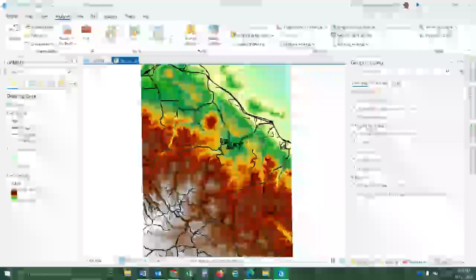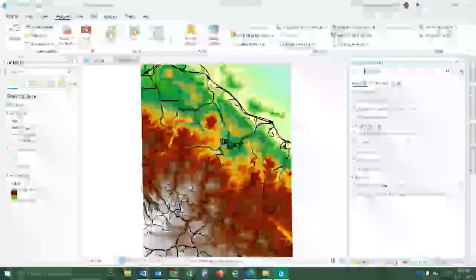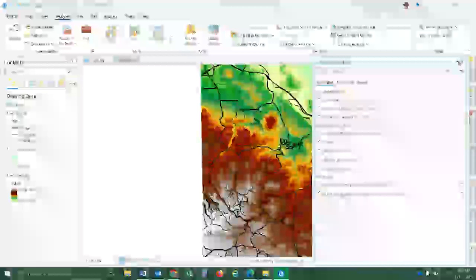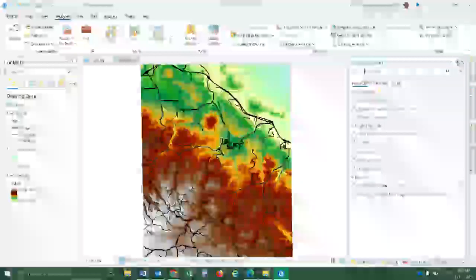Moving on to step 2 is having you double check to make sure your geoprocessing pane is pinned, which if I were to close geoprocessing, pretend that's closed, you get to it by opening up Tools here. And if this pin is in the downward position, it's pinned. You can hide it. And if it's out like this, anytime you click on something else, it goes away. But if you click on the pin, it pins it in place, and no matter what you do, it's still there. So we're going to open the Reclassify tool first.